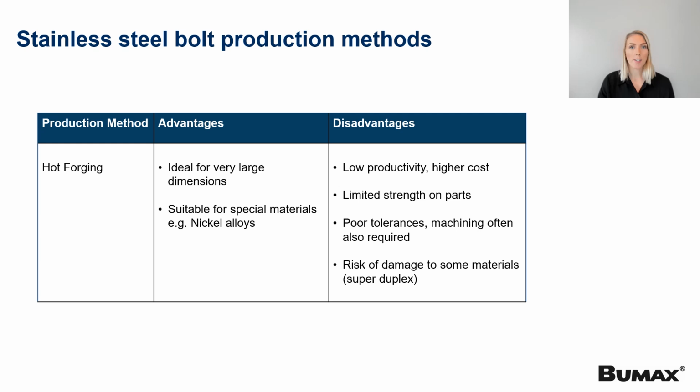Hot forging is performed at really high temperatures. The increased temperatures help to avoid strain and hardening, as well as lower the stress flow and amount of energy needed to deform and shape metals. Heating causes the metal to become more ductile. When the pressure of the dies squeezes the hot metal, the structure transforms into a more refined grain that results in increased yield strength and ductility.